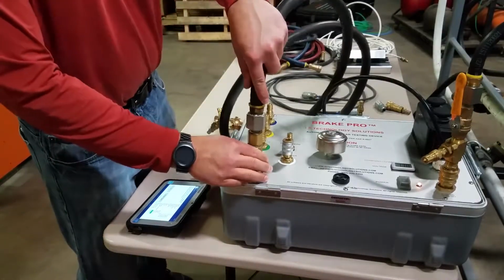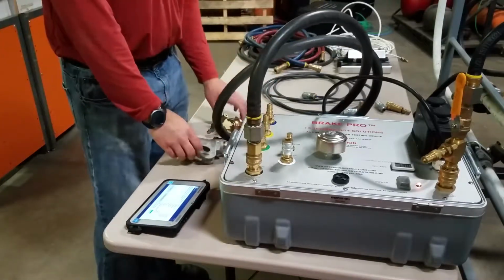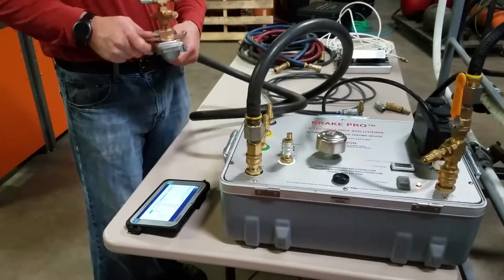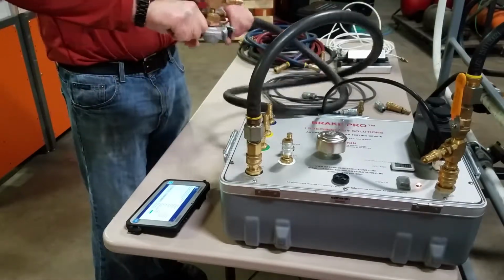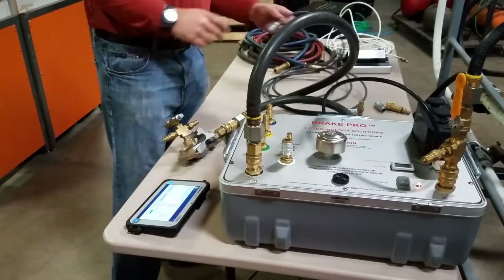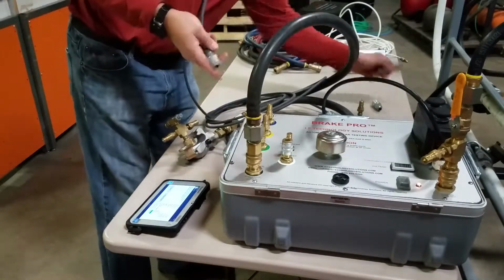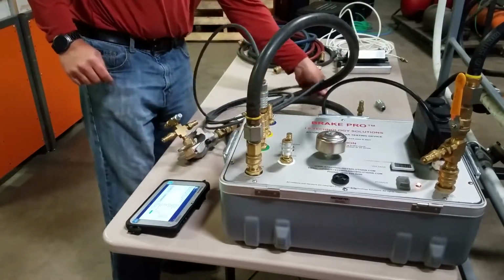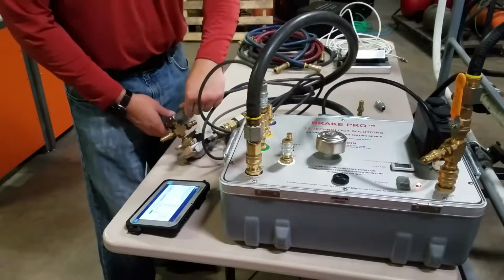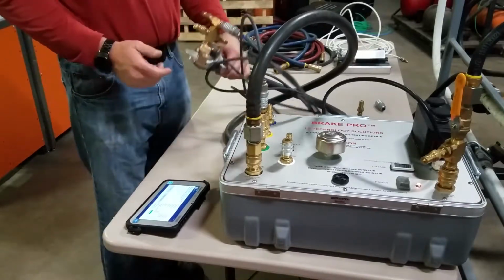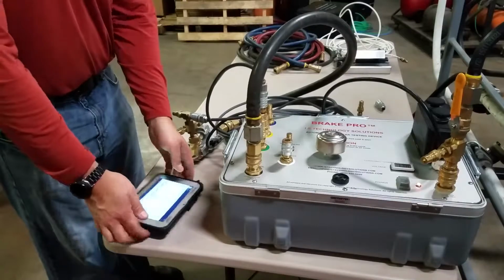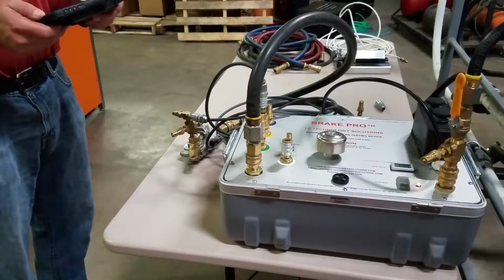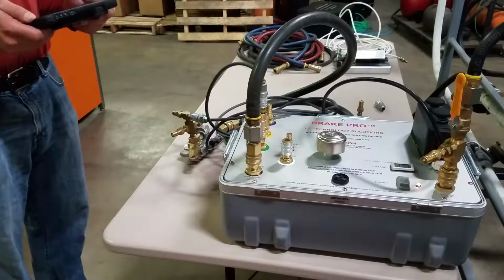The instructions will then tell you to connect the brake pipe hose to the device and then to put a dummy coupling in the brake pipe glad hand. The brake cylinder hose is then connected to the device, and the other end is connected to the dummy coupling to create a common air loop between the brake pipe and brake cylinder for the daily test. Start the test on the tablet, and the test will run.